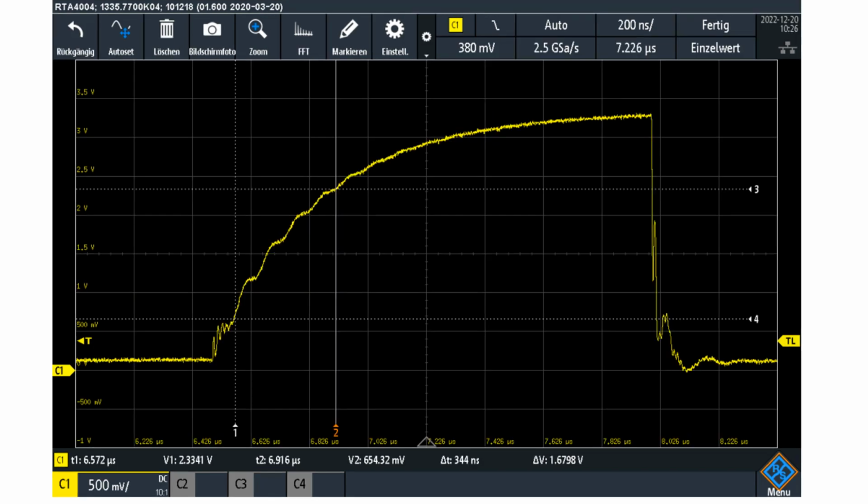Our final measurement is 1 kiloohm pull-ups plus multi-layer surface mount ferrite plus TVS diode array plus that 20 centimeter cable. Also included is 400 picofarad of MLCCs, which equals 344 nanoseconds rise time.